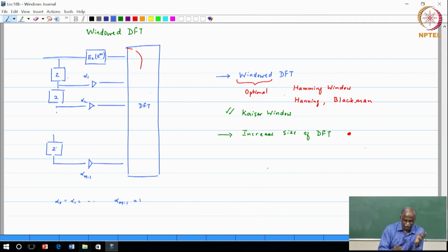You have to be careful when you write this. Let me erase this portion and indicate that this does not have to be a constant, it could be a polynomial. And of course, you can change all of them to be polynomials, they do not have to be the same, they can be different, and that takes us back to the DFT based filter bank.